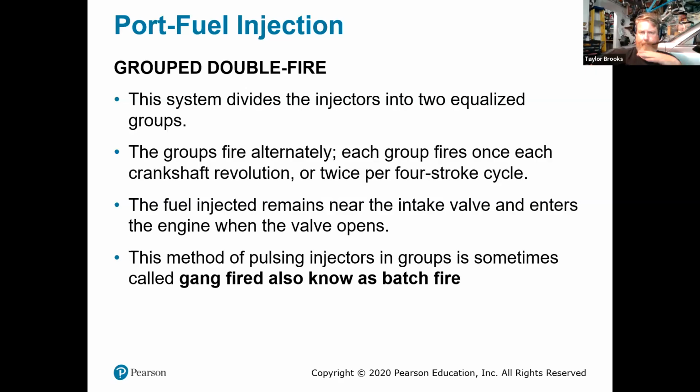We're going to have cylinders that are partnered or paired, in that one will be at exhaust top dead center, one will be at compression or power stroke top dead center, one will be on intake and one will be on exhaust. So we're going to try to match the cylinders that are drawing in air at similar times so that we can maximize the amount of fuel getting into the cylinder.